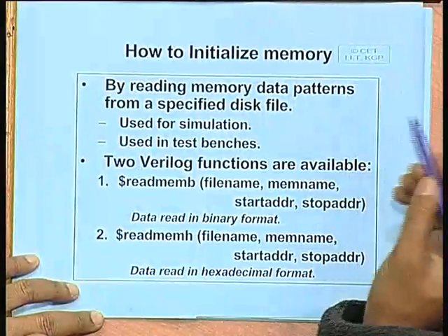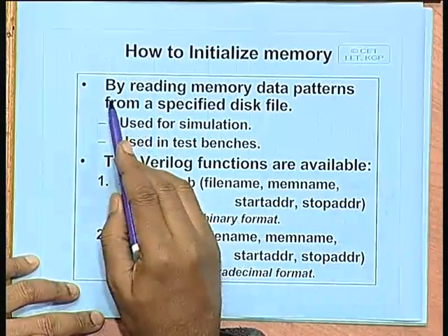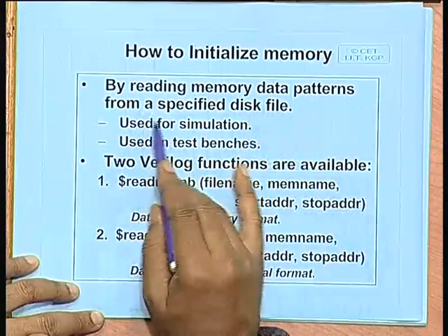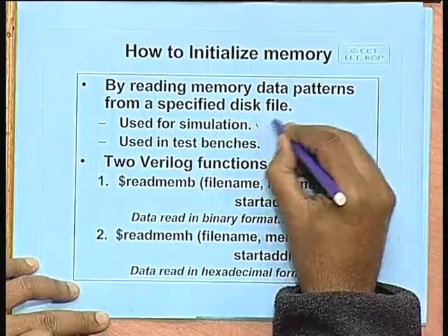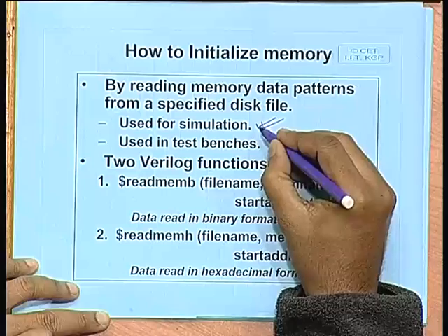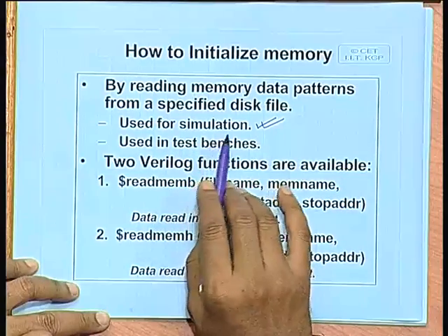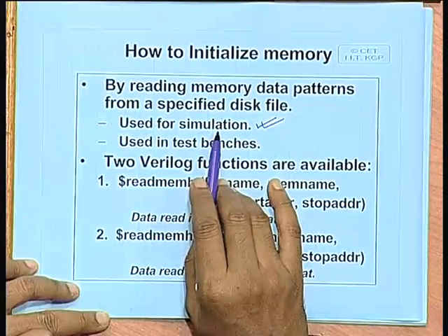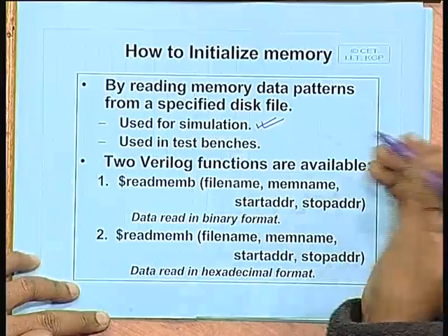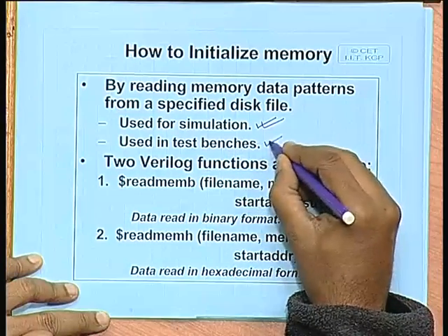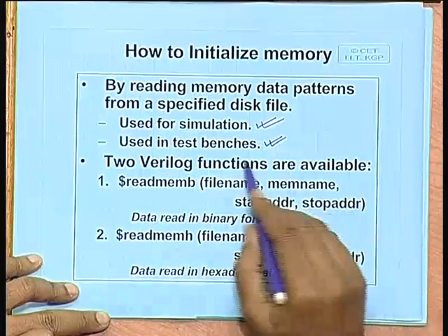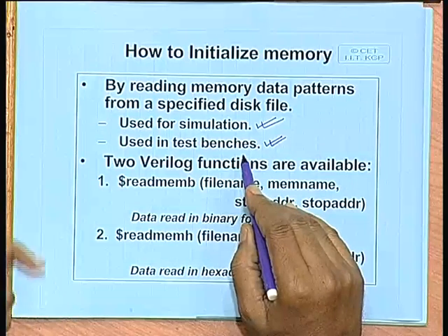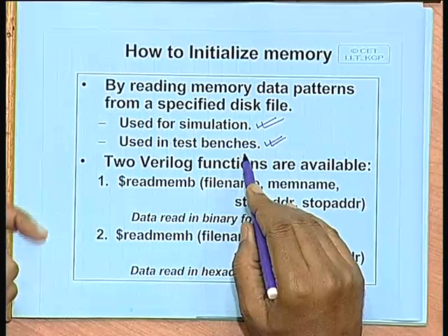So, this is one very common way of initializing memory by reading the data patterns from a specified disk file. This, as I told you, is used for designs where you only want to simulate something, not synthesize, or, as we will see later, when you are using a test bench, where I want to generate the test patterns that I need to apply to a circuit I have already designed for the purpose of testing.